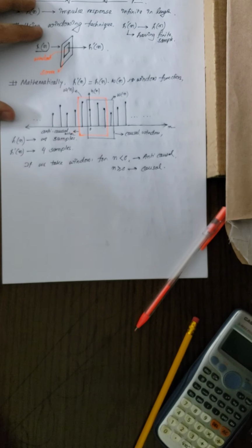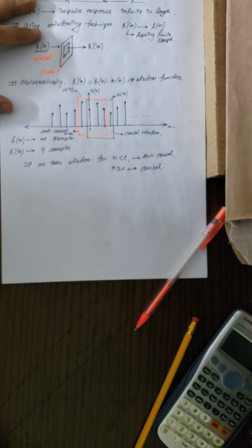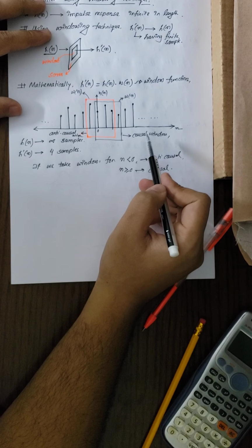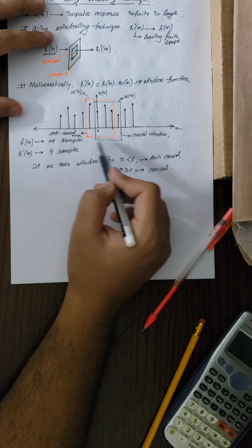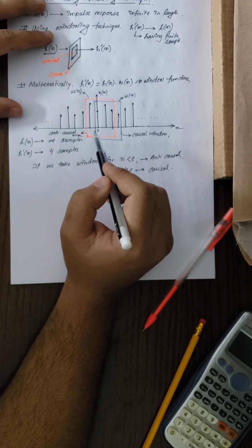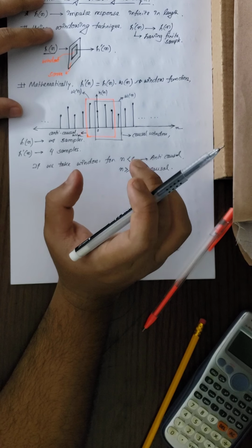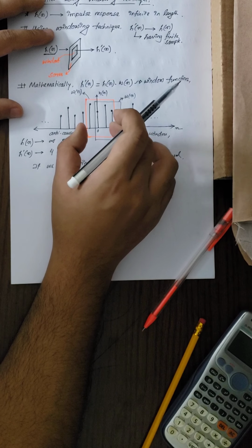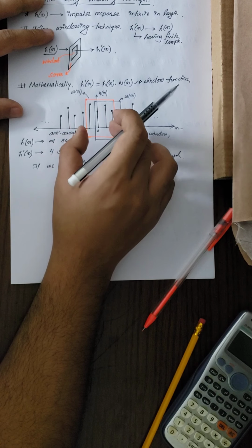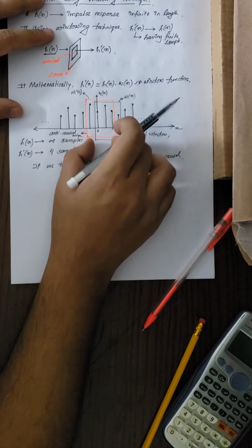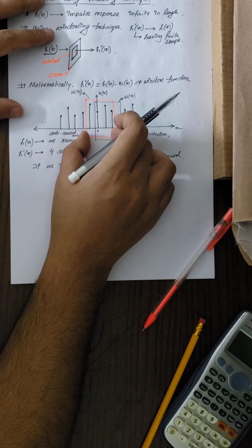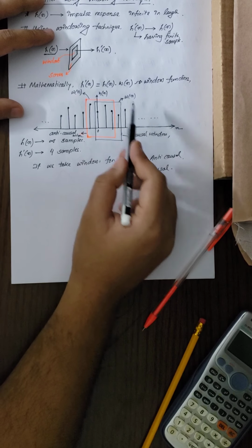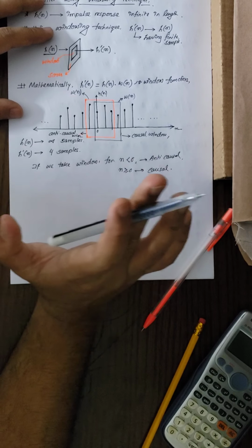Now in linear phase, we have discussed that all the filters must be causal in nature. So anti-causal window is undesirable. Although we can design anti-causal window, what we need to do in order to make the window or the filter feasible is, after designing this anti-causal window, we can simply shift it by the required number of samples to make it causal. And that way this will also work.